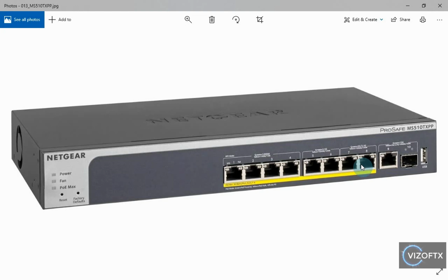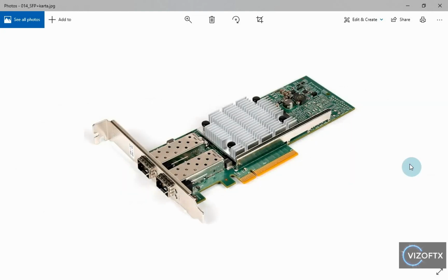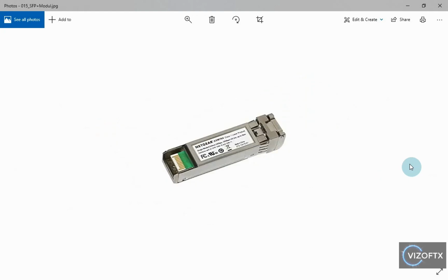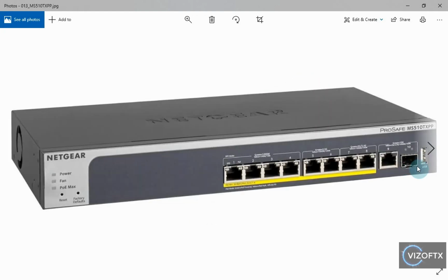We connect these switches to the PC using a 10 gigabit line, either metallic, which allows a Cat6 cable connection up to 30 meters, or with Cat6a you can pull up to 100 meters. And, for example, if you want a higher distance, which can be done even at 2 kilometers, you can use the optical interface 10GBASE-SR SFP+ of this switch. Of course, in combination with a suitable PCI Express card and a PC that supports such an interface, and a module that you insert into this port.